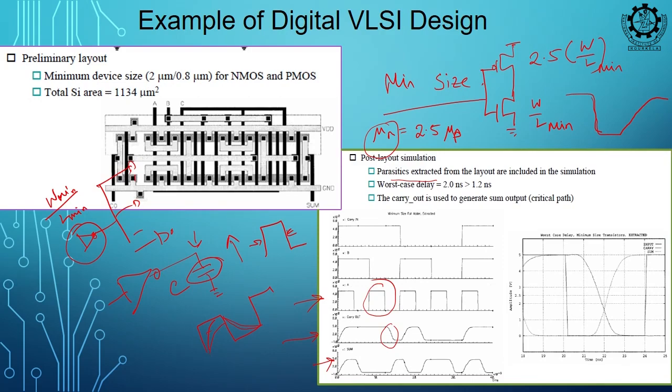One is for low power, one is for high speed. Low power is generally for minimum design, but when you are connecting it to what is known as fan out, right, if your fan out is more, you have to be careful about the sizing, because otherwise this kind of scenario will happen and it may not be able to drive. But L should always be minimum.